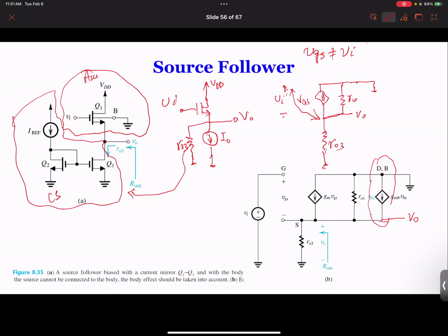What we can do is certainly write a node equation around this node over here. And here we need to be careful that VGS is not Vi. So if you look at Vi in this example, Vi is equal to VGS plus VO. I think that's important that we get here. And then we can write a node equation based on that node.